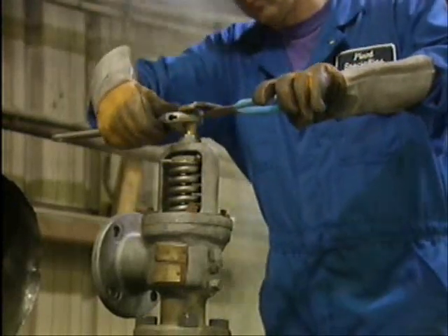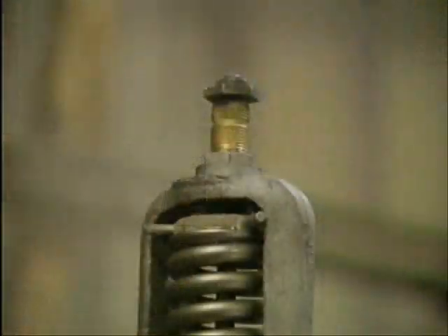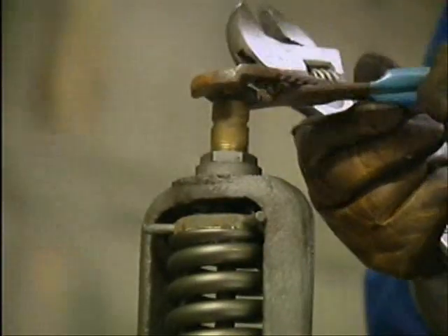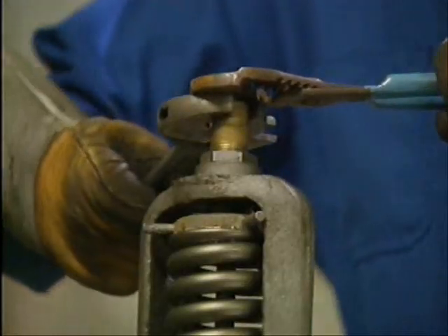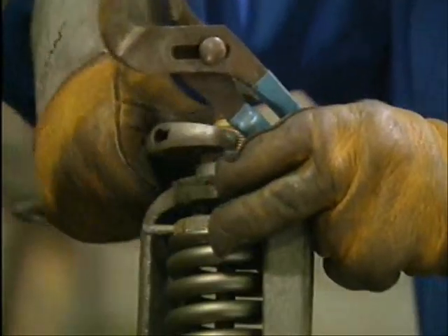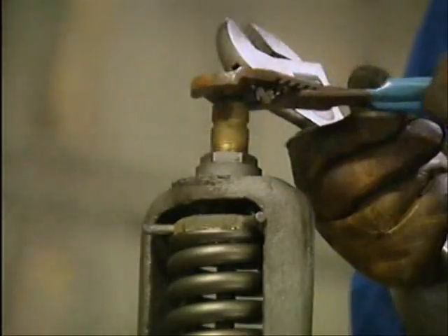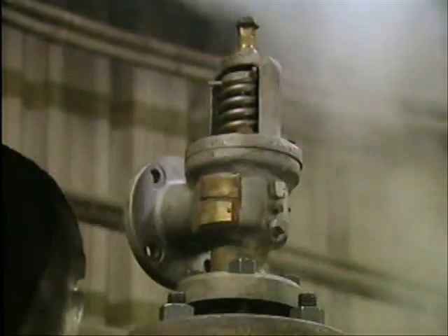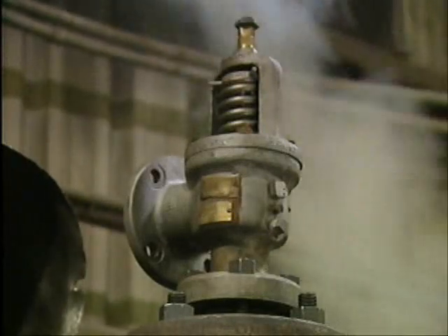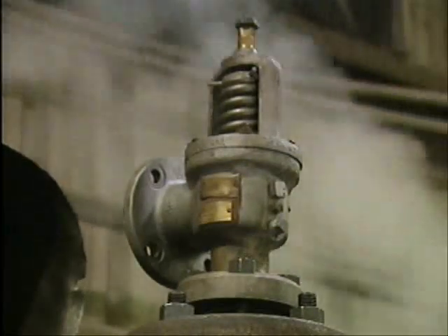If you try to turn the compression screw without loosening the lock nut, you'll probably damage the screw. Which way you should turn the screw depends on whether the valve is opening too soon or not soon enough. For example, if the valve is opening too soon, you should tighten the compression screw by turning it clockwise to increase tension on the spring. On the other hand, if the valve is opening too late, you should back the screw off a bit by turning it counterclockwise to relieve some of the tension on the spring. After you've adjusted the compression screw, test the valve again to see if it's been set properly. Usually, you need to make several adjustments and tests to fine-tune the set point of the valve.